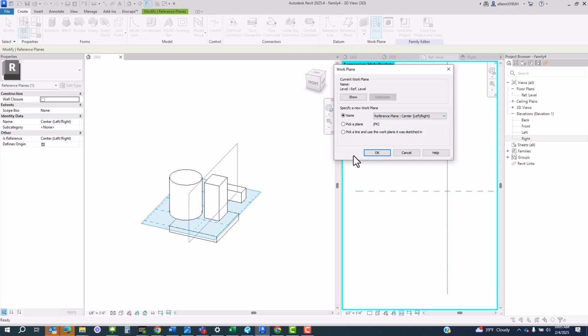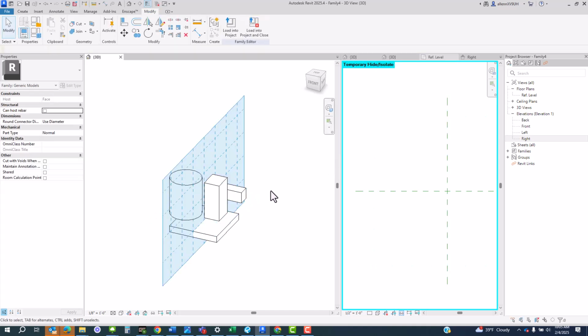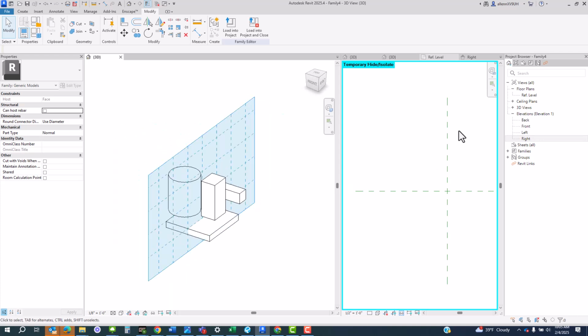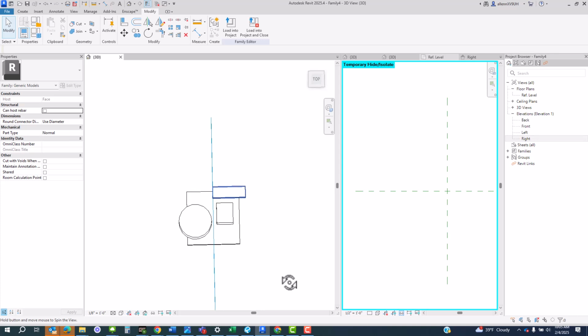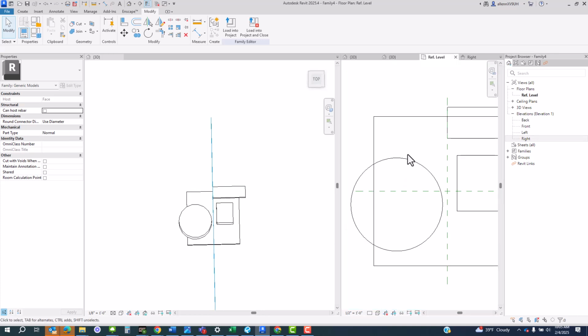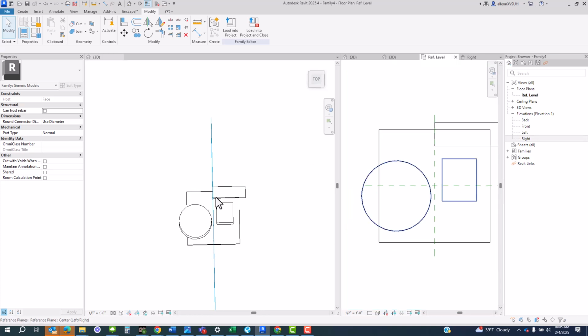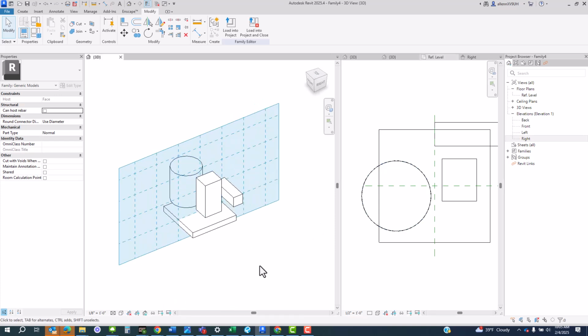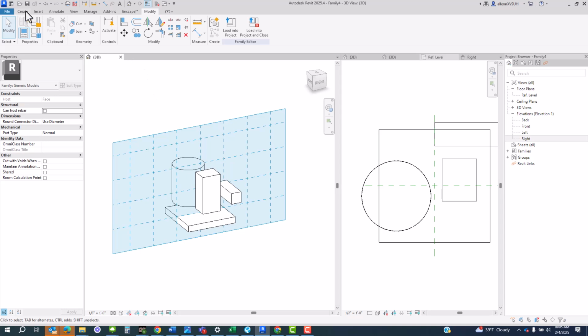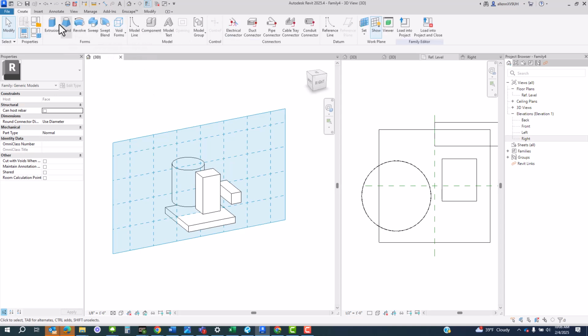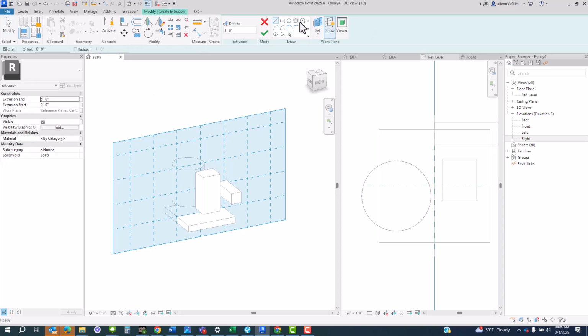That's the one we said we were drawing on. And then click OK. And sure enough, there's that piece of paper. It's represented by this line. Looks like that. Let's unhide everything so you can really see that relationship. And in 3D, I'm able to rotate it so that I can see it. But now, once again, I can create any shape that I want for an extrusion, and it starts right here.